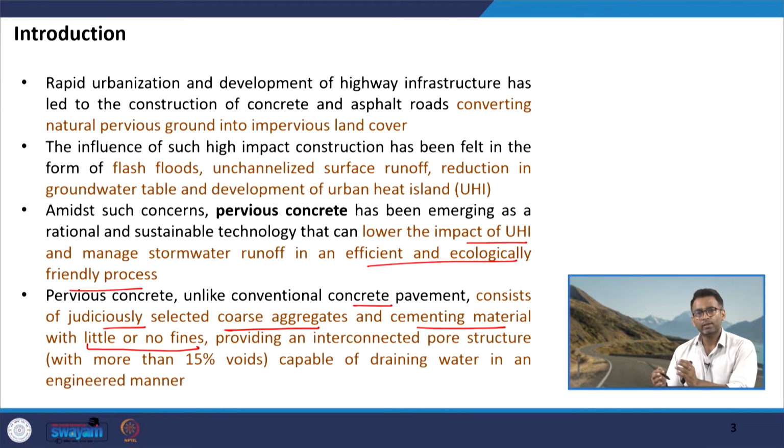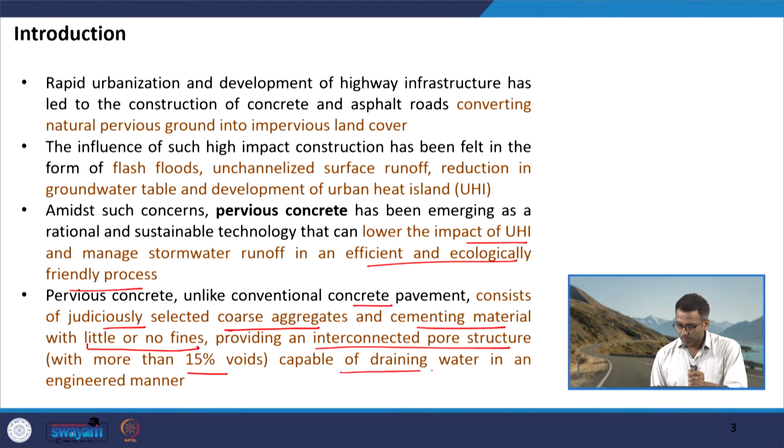And once this skeleton is created, once this mass is created, it provides an interconnected pore structure within the skeleton, and the void content in this particular mass is typically kept above 15% to facilitate the movement of water, okay. And it imparts draining capability to the structure, that too in an engineered manner, because we are creating the interconnected voids, okay.